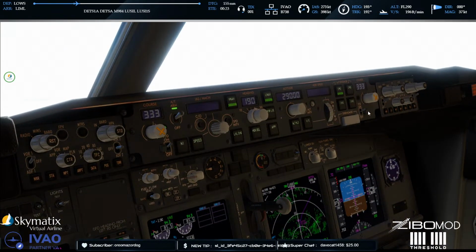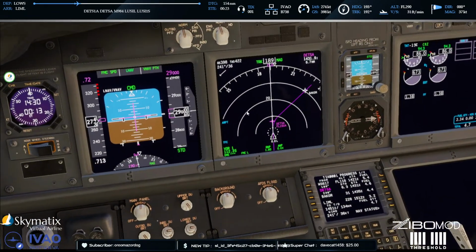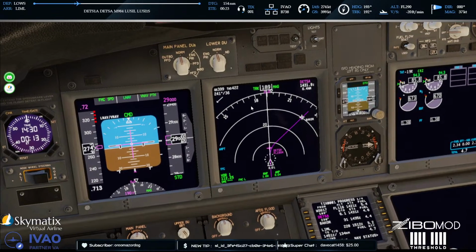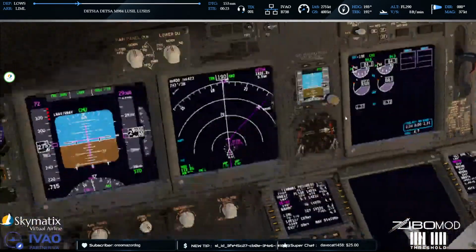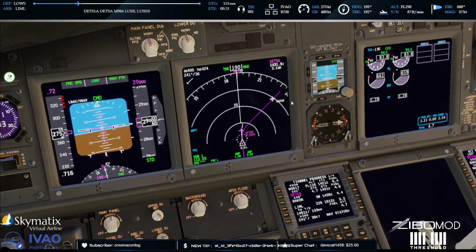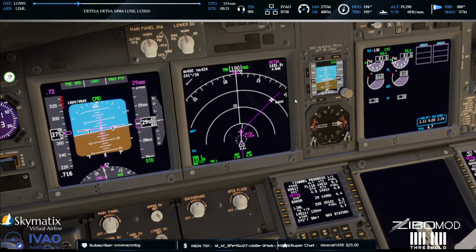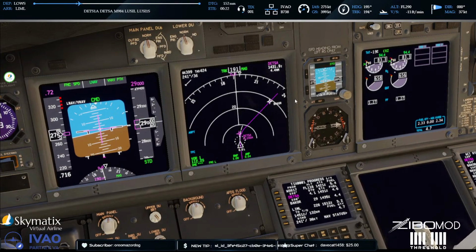Once you switch off these two flight directors, those are the main things. If you switch them off, it should cycle the LNav, VNav. Because what could be happening is you could be trapped in your approach mode, and you get out of your approach mode by switching off your two flight directors. I'm not sure why it's happening to you, because I don't think it should happen that way. Once you press TOGA, it's supposed to cancel it. It's supposed to go into the GA mode to go around.